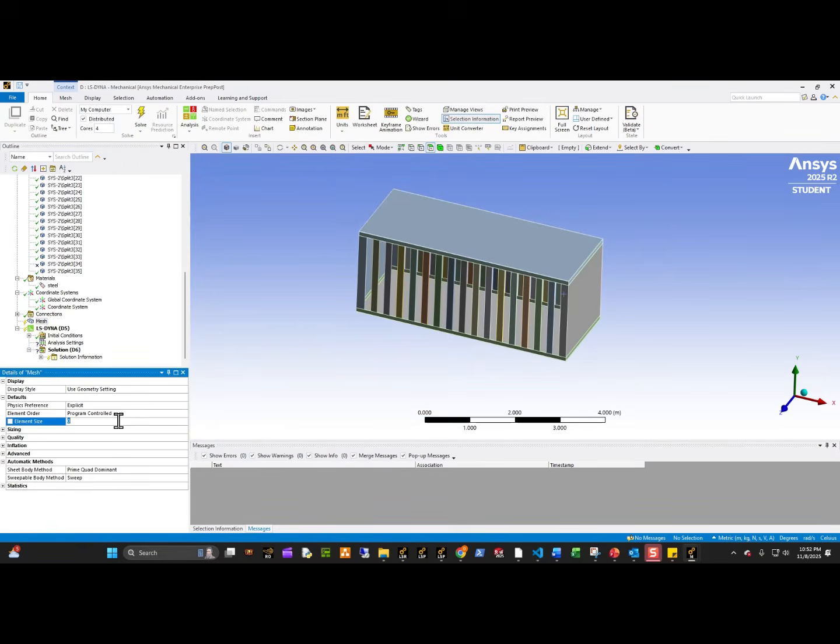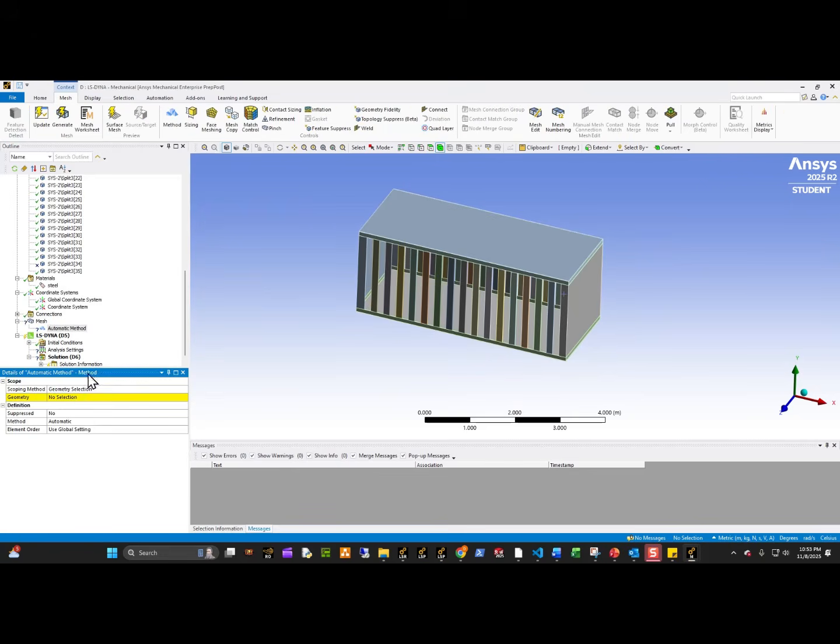Okay, in terms of meshing, I'm going to make this super simple. I'm just going to do 0.020, 0.040, and I think because of the way I did this, I have everything as the swept body, like that, so I don't have to worry about it. Let me double check my original setup to make sure I didn't miss anything. Oh yeah, I guess I should do a sweep. Oh, I don't have any named selection created, so let's just do this.